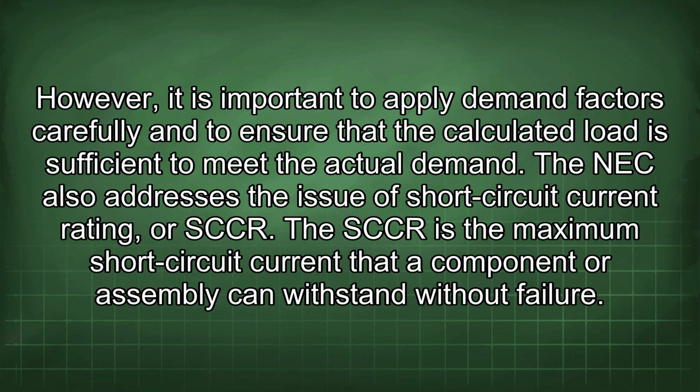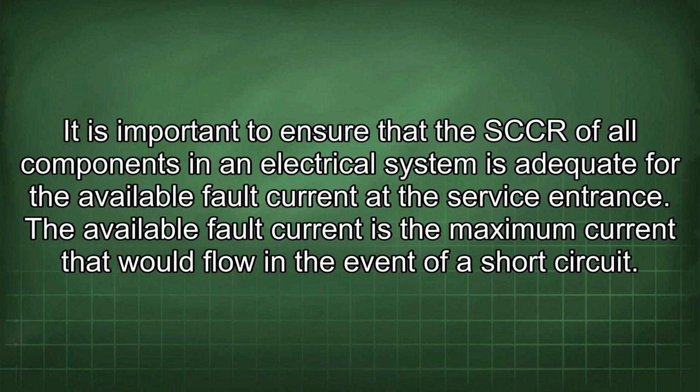The NEC also addresses the issue of short circuit current rating, or SCCR. The SCCR is the maximum short circuit current that a component or assembly can withstand without failure. It is important to ensure that the SCCR of all components in an electrical system is adequate for the available fault current at the service entrance.